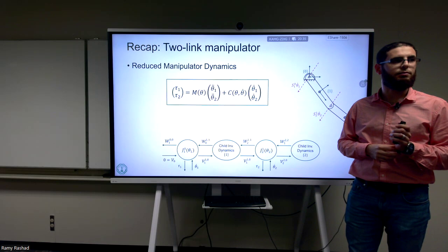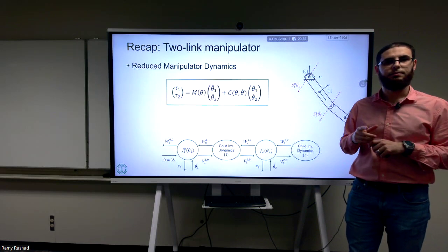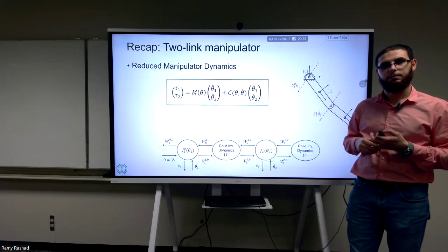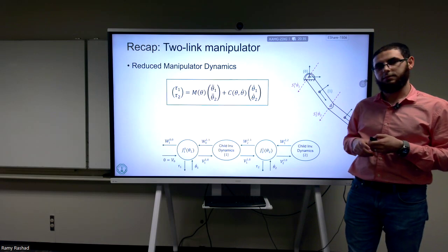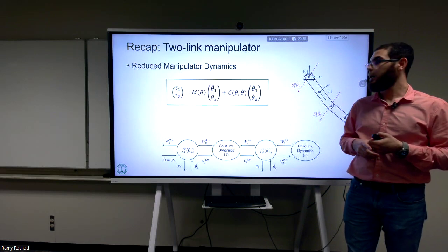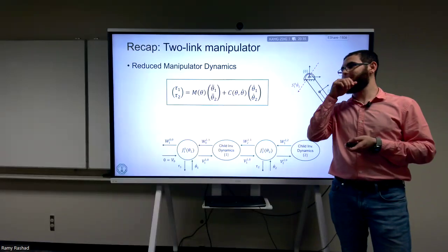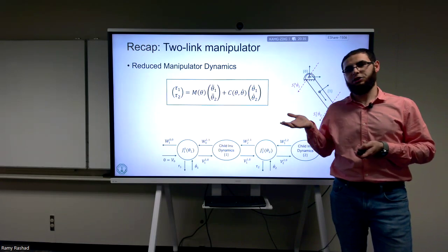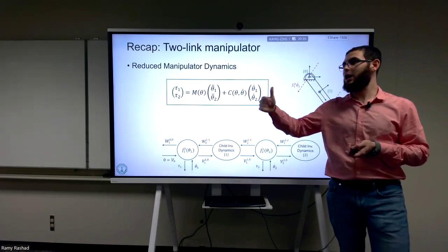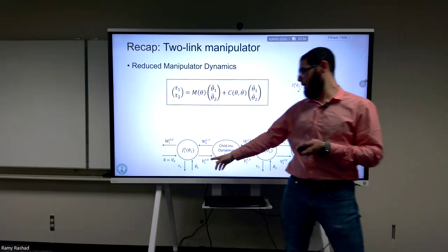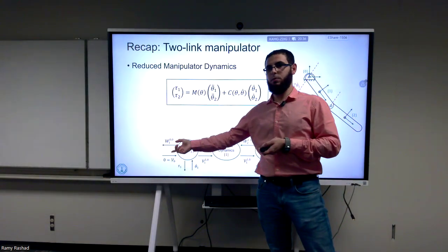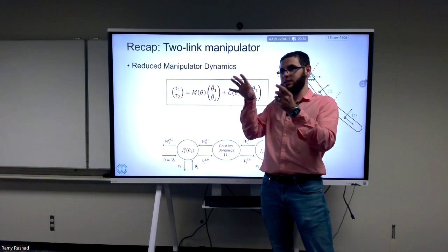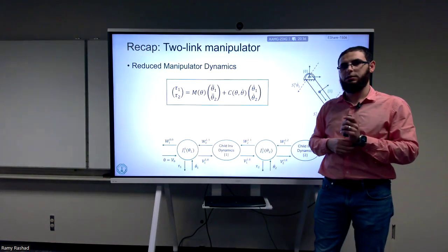Any more questions? Sorry, sir. Yeah. The control allocation, isn't that what we treated when we were dealing with quadrotors? That's right. But then we mentioned that it's supposed to be the inverse of the transpose of the Jacobian. Yes. But then we're already dealing with the Jacobian here. What we did there is that we derived the control allocation directly as a wrench, we didn't derive it using a static wrench analysis as the transpose of some Jacobian that relates the theta dot to the bodies. You can do it and you're going to get the same result. We didn't do that. That's why it's related to the Jacobian, but it's not clear at first sight what it is.